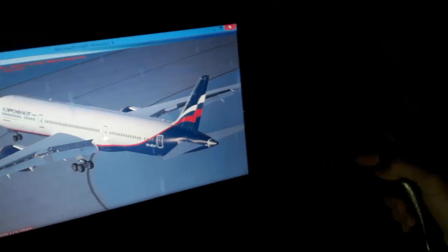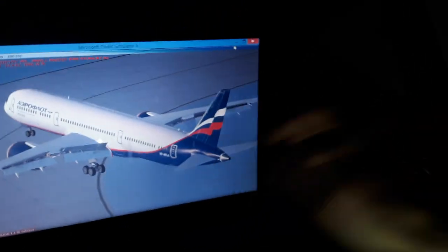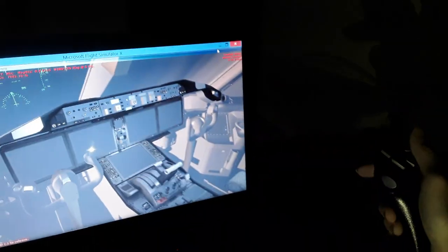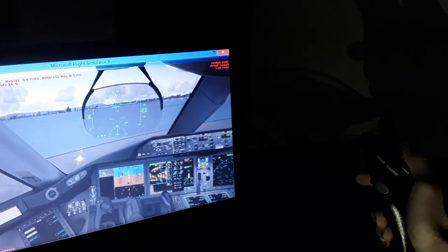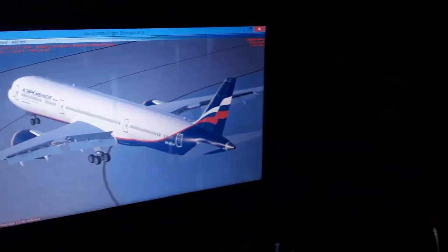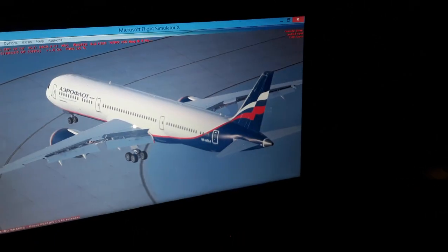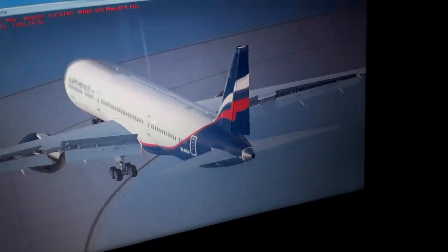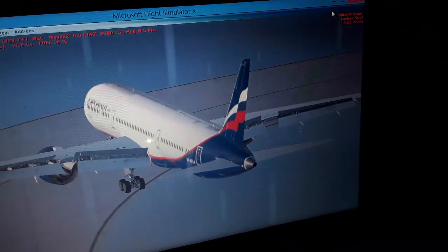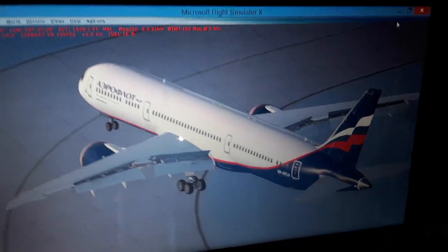So this is also controlled by the computer automatically. In the landing process the inverse is done, so it comes back to function below 80 knots when you land, because we take off and we land at an airspeed of like 140 knots, like 250 kilometers an hour, much higher than that. So you use the rudder to control the steering of the aircraft in takeoff and in landing mainly. And then as you slow down in the landing, you have the nose wheel coming in.